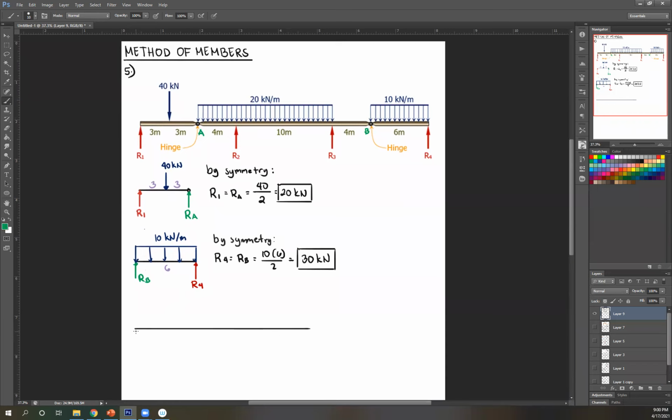So draw. So remember, when you have assumed direction previously already in other members, remember, if you have a connecting member, it's the opposite direction. So here, RA, this is upward, therefore on the connecting member for this segment, this should be downward. Okay, so this is now RA. Reactions are the same. This is R2. This is R3. And once again, you have a reaction here, B. I assume B is upward here. So now do the opposite for that, downward.